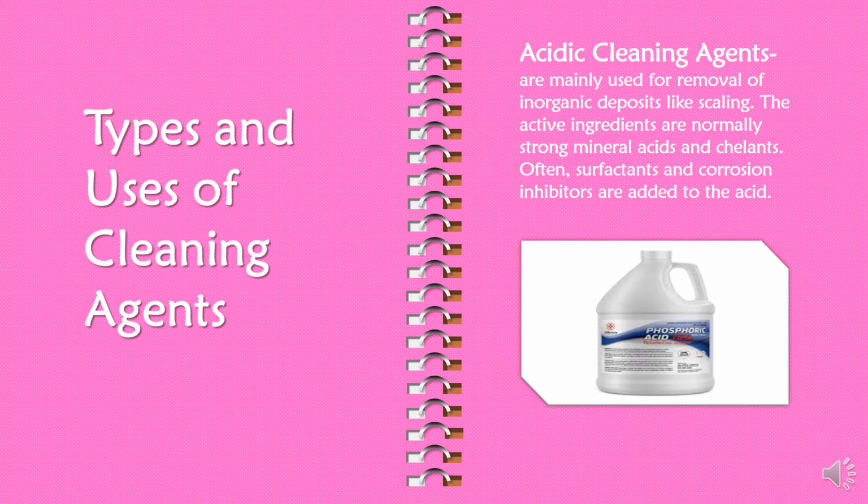Another is the acidic cleaning agents. These are mainly used for removal of inorganic deposits like scaling. The active ingredients are normally strong mineral acids and chelants. Often, surfactants and corrosion inhibitors are added to the acid.